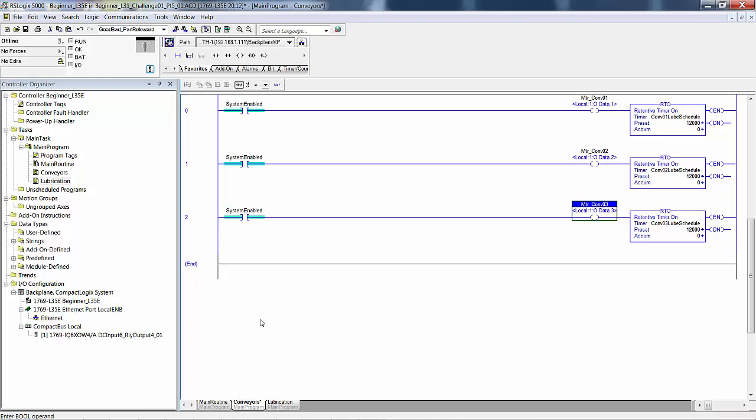When conveyor 3 calls for a part, and if both conveyors 1 and 2 are full, and there is another part ready at the entrance of conveyor 1, all 3 will run until the new part is fully onto conveyor 1. At that point, conveyor 1 and 2 will stop, but conveyor 3 will continue to run until that part was pulled onto conveyor 3 and has exited conveyor 3 completely.